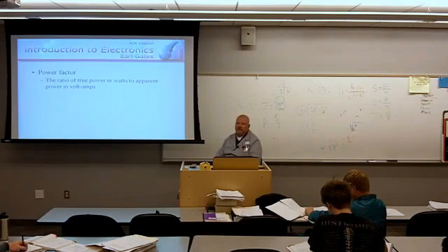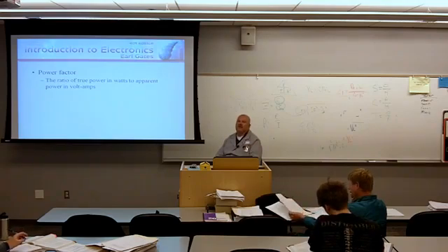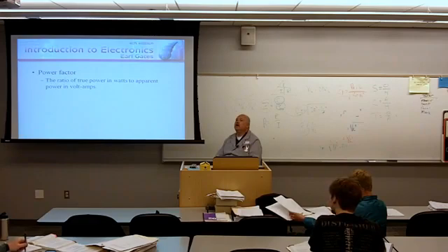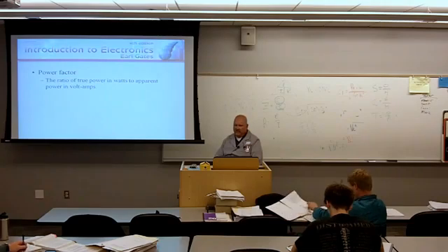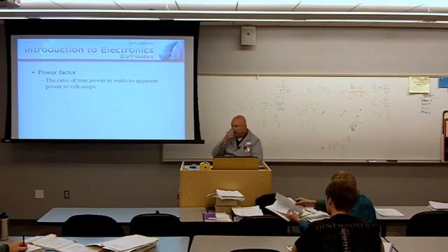Power factor, the ratio of true power in watts to apparent power in volt-amps. True power is measured in watts because true power is the only power that's actually being consumed in the purely resistive element of the circuit. Is the reactive element of the circuit consuming any power? No.